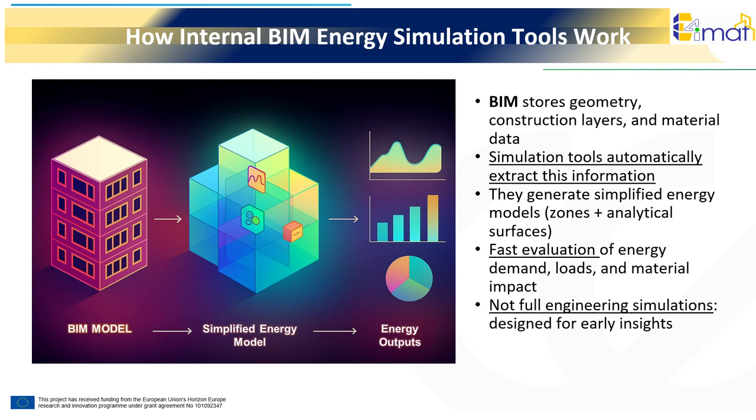Understanding how internal BIM energy analysis tools work is essential for evaluating building performance early in the design process. These tools are fully integrated within BIM platforms to provide fast, early-stage insights. They automatically read the building geometry, construction layers, and material properties from the BIM model, and use this information to generate a simplified energy model composed of thermal zones and analytical surfaces.